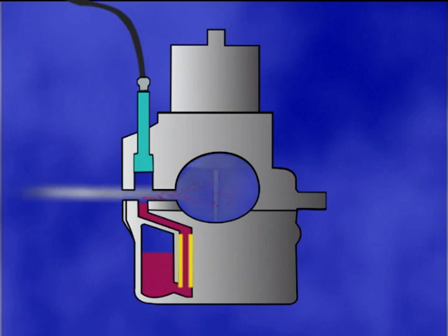This port is located between the engine and the throttle slide. An enrichment circuit works best with the carburetor slide closed. High vacuum behind the closed slide can then easily draw air and fuel through the enrichment circuit.